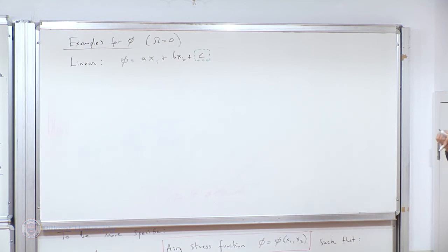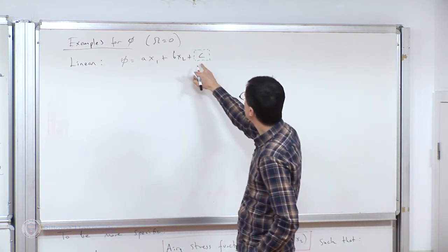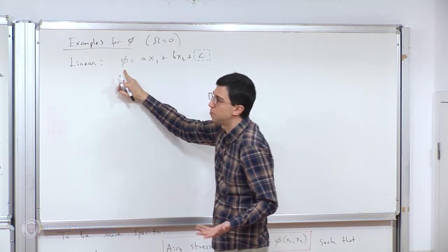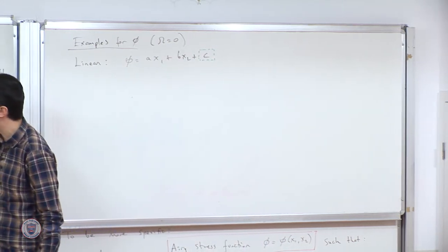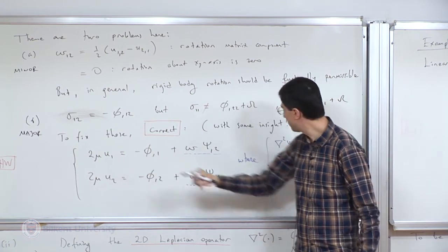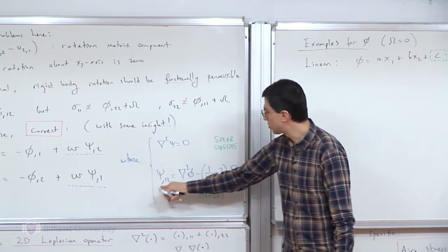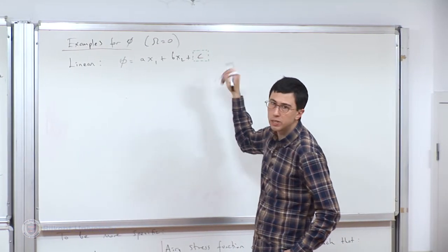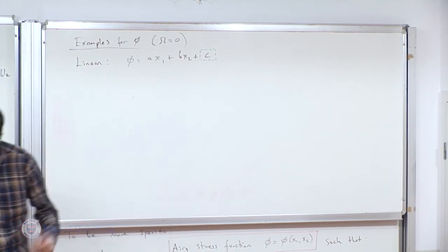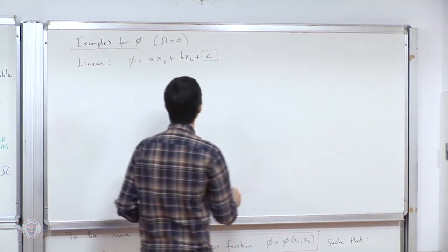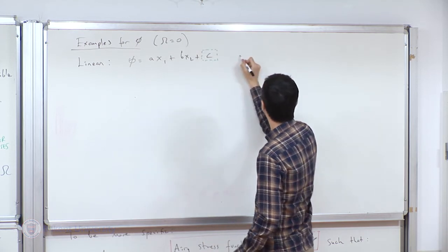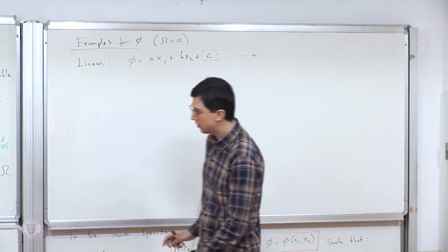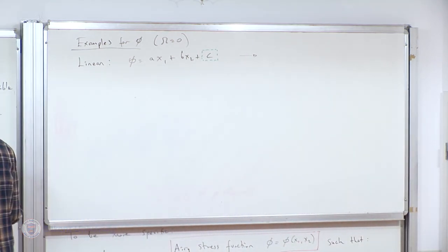At this stage, what you should immediately recognize is that constants of the Airy stress function have absolutely no physical significance because the stresses require two derivatives, displacements require one derivative, and eventually, if you like to solve for psi, it also requires derivatives of phi, and therefore, this thing will always die. So this is of no significance. So really, I could have only put phi in there, A and B there. This is not necessary. So now, first of all, one thing we can recognize is that, actually, let me pull up this board.